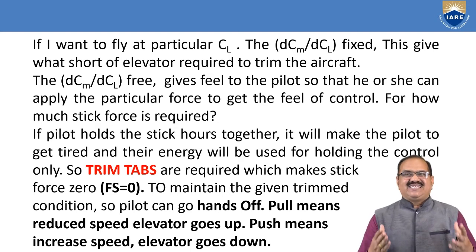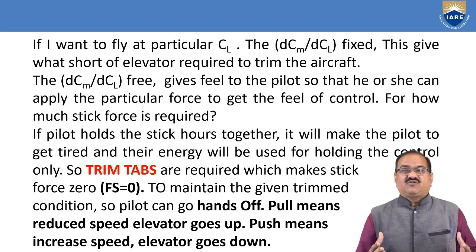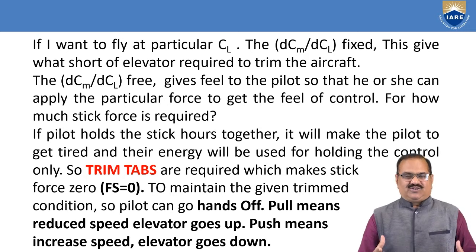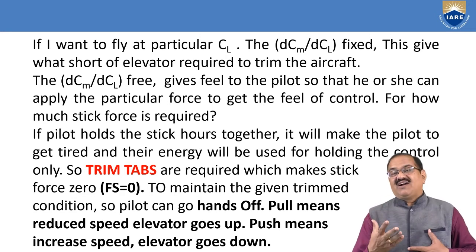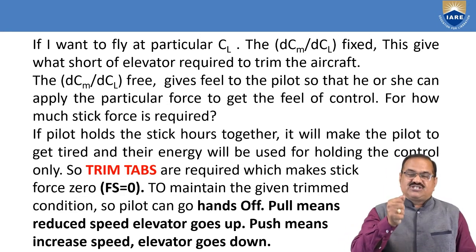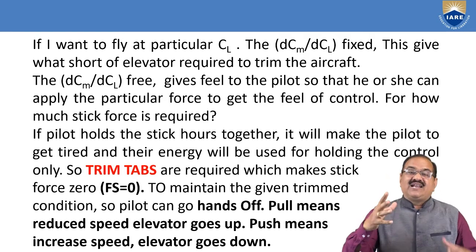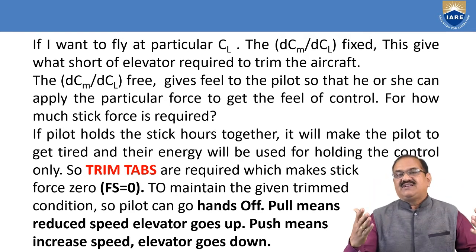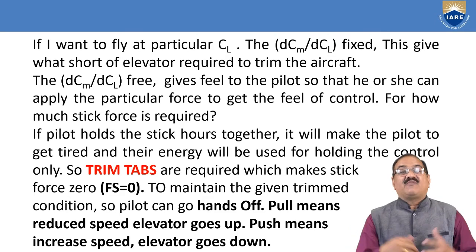The dCm/dCL stick free gives feel to the pilot, so that he or she can apply a particular force and get the feel of the control, for how much stick force is required. So the feeling of the pilot is also important. He feels how much force is required, so he can understand at which speed or which CL the aircraft is flying.